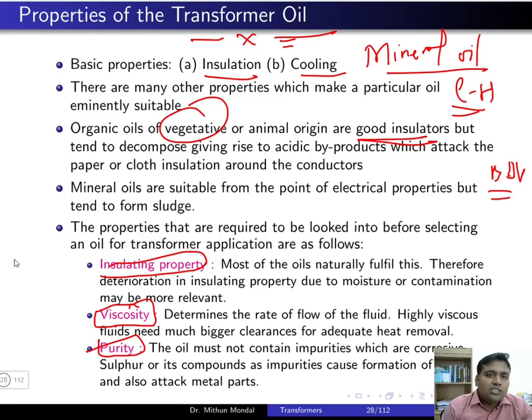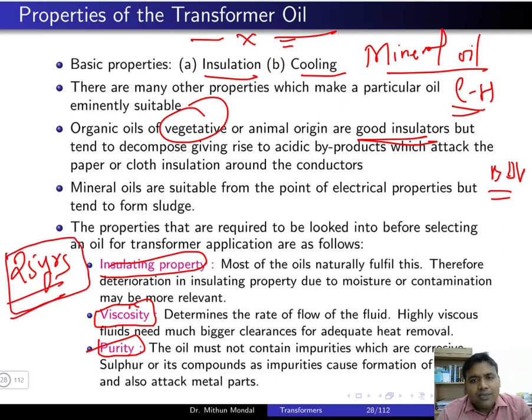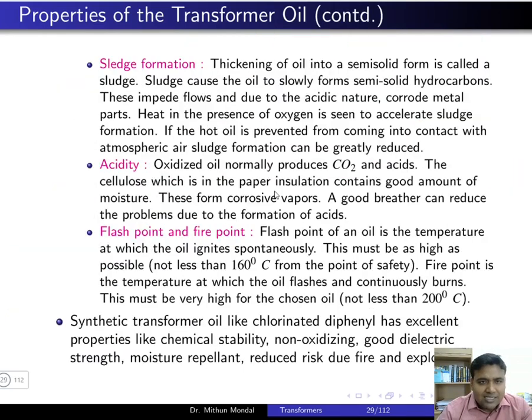Generally, a transformer has a lifespan of 25 years. So 25 years is the general lifespan of a transformer. If you keep the transformer in good health by periodically testing the transformer oil and removing the acidic products. Generally, acidic byproducts are formed which go into the transformer in the form of sludge. Okay, due to the heat of the transformer, there is a breakdown of the insulation in the winding, and this insulation goes into the oil and is deposited in the oil in the form of sludge. So they have to be tested.